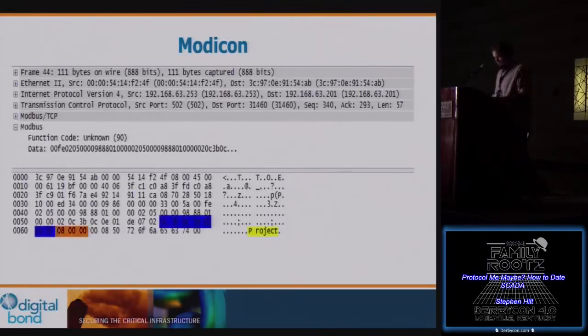Let me skip through the transitions there. The version at that time was 008, which is stored in Little Endian at the bottom. The project name is highlighted as well. And then the date timestamp is fairly interesting. It's also in Little Endian. 07DE is 2014. 01, it was January when it was last configured. It took me a long time to find that, because who honestly stores a date timestamp that way? It's not usually the normal way, so it took me a while to find that one.